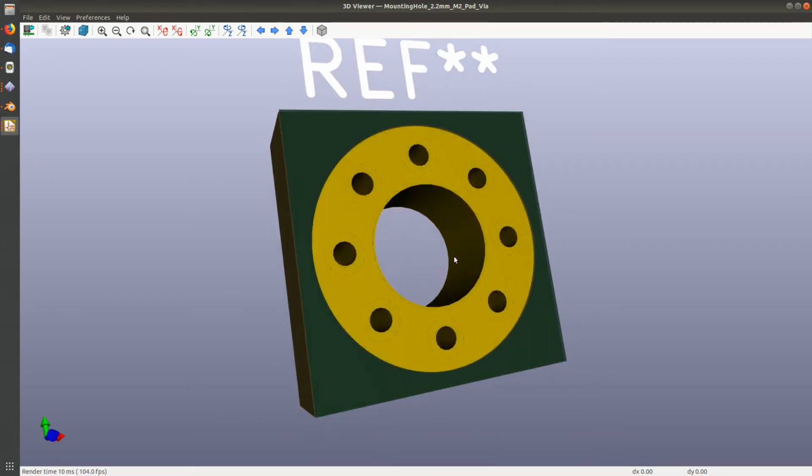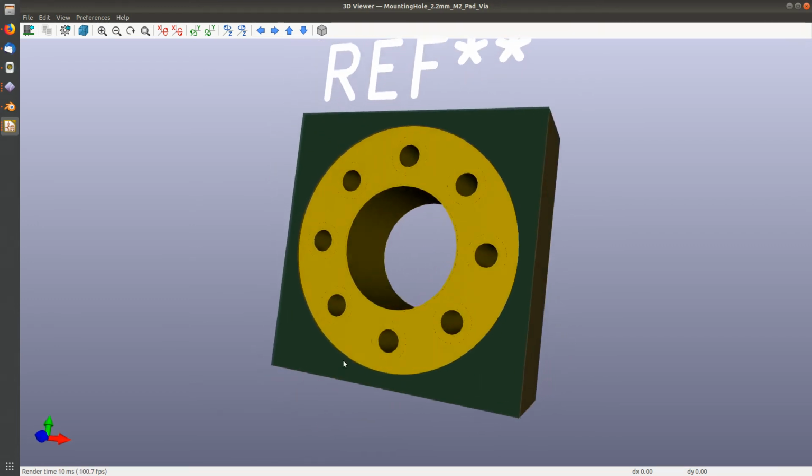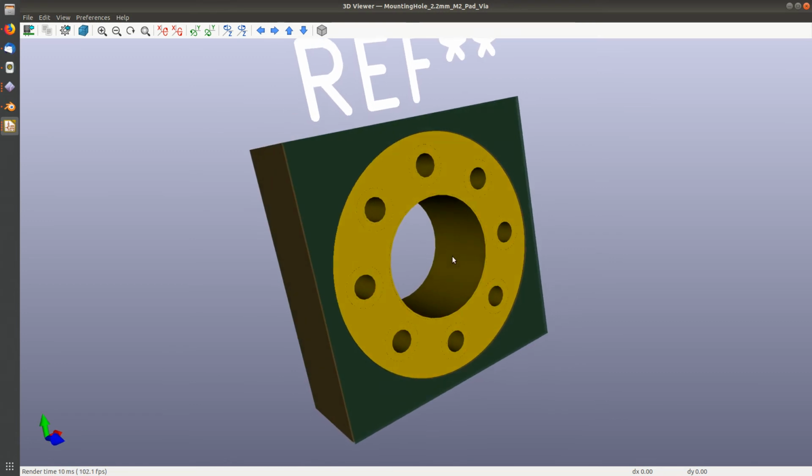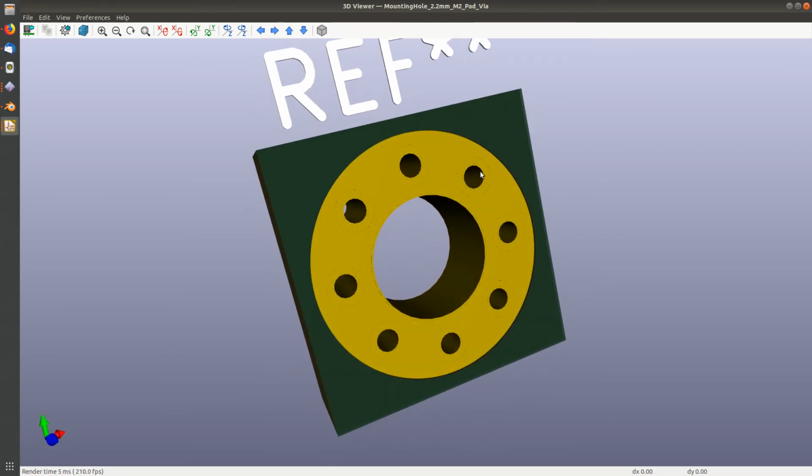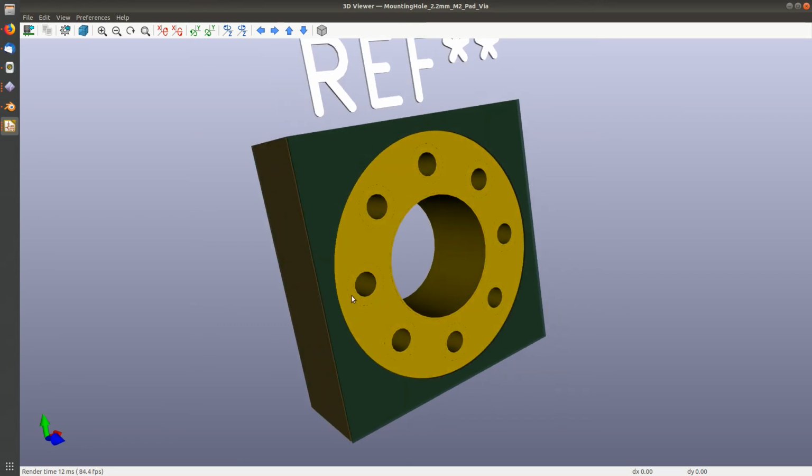That's why I'm using my 4-layer design, by the way, for this video, instead of starting a new 2-layer one. These will run through the board and do a better job at connecting to the internal planes, if this is supposed to be connected to the internal planes, than just this one single plating that's inside here, all right?